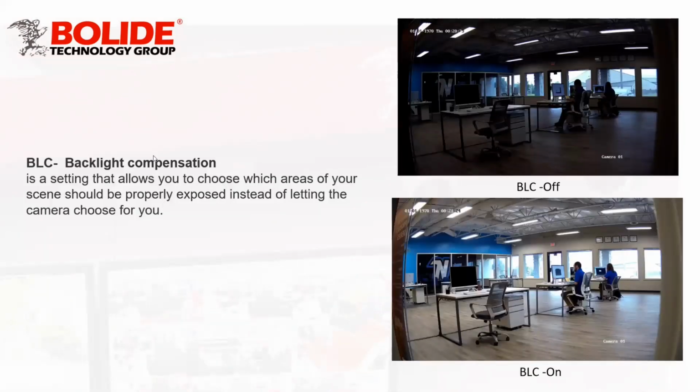The other one would be backlight compensation, BLC. It's a setting that allows you to choose which areas of your scene should be properly exposed instead of letting the camera choose for you. So this is very similar to WDR. The difference is that you can control what areas you want to set this setting on. For instance, in the picture here, it's very dark on top and light on the bottom. You actually choose how you want the camera to produce the image, whereas WDR lets the camera decide. Backlight compensation lets you decide. That's the difference between the two.